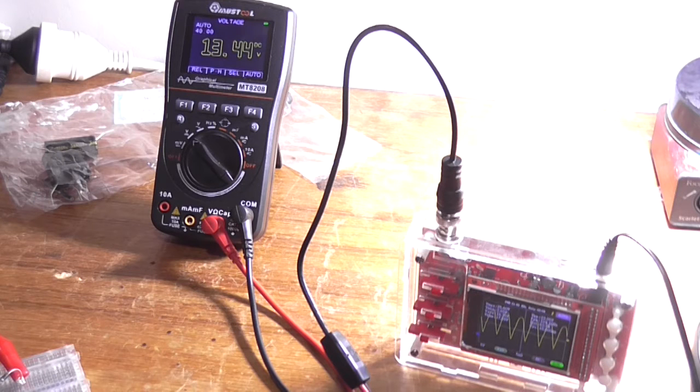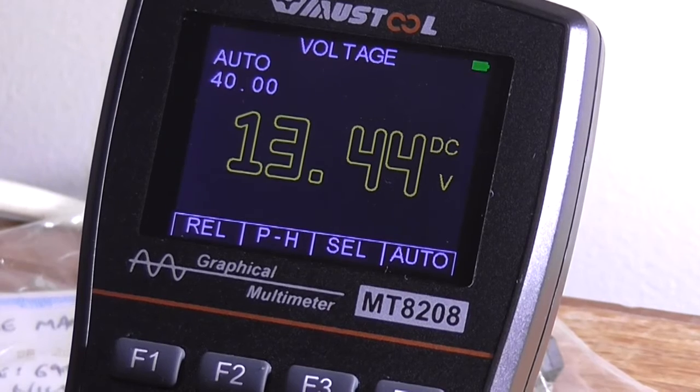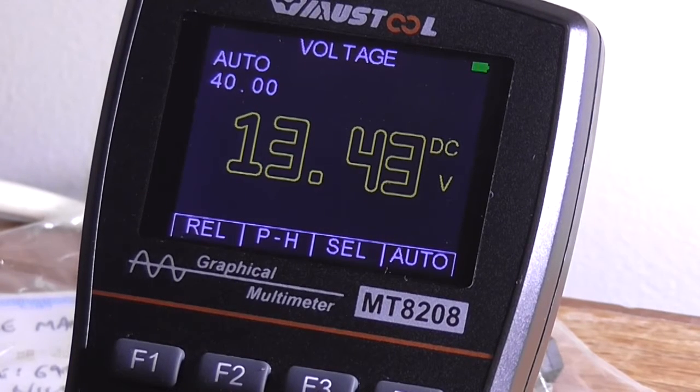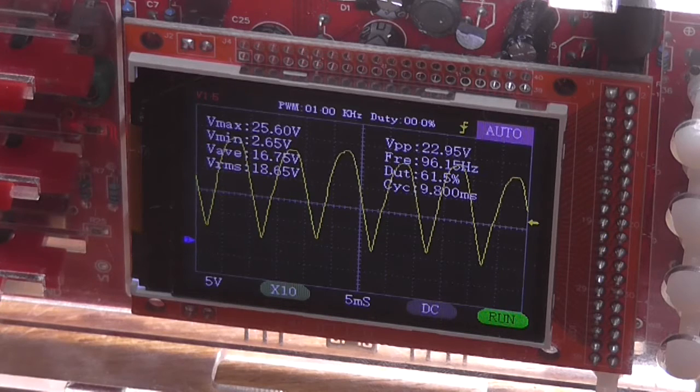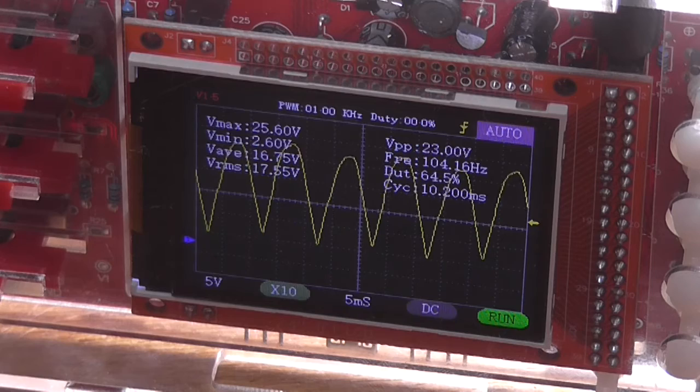And yeah, as we can see, we've got close to 15 volt. It's not quite 15 volt, that's only because probably of the diode drop of each of those diodes, which is 0.59 volt, something like that. And as we can see on the waveform, there are no missing peaks, there's no dead time. That is why it's called full wave.